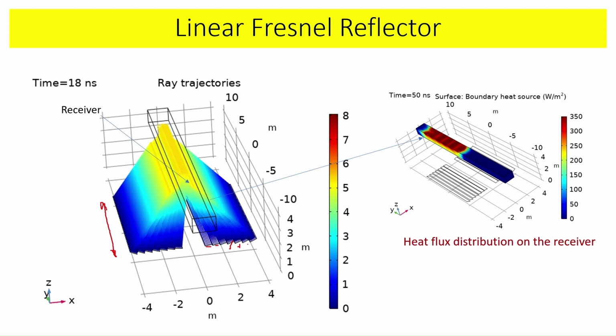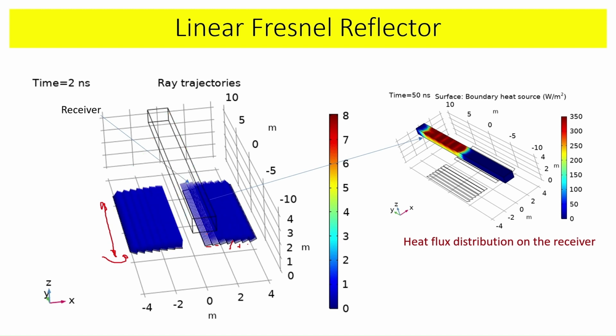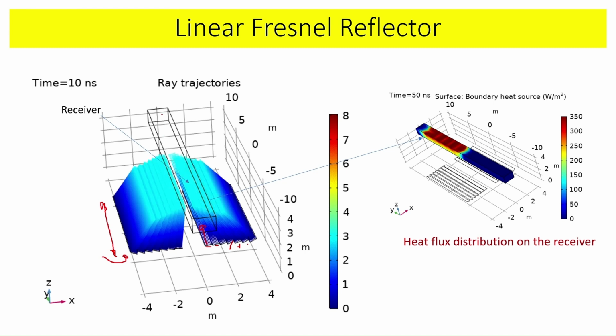Okay, they are rotated like this as the sun moves from one location to another. So we need to adjust the tilt of these mirrors so that they all the time focus the solar radiation on the absorber, because the absorber is the place where the working fluid is flowing, which we have to heat up. Right?